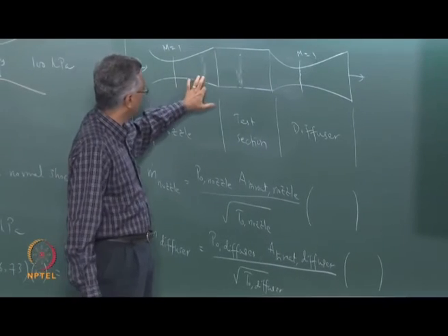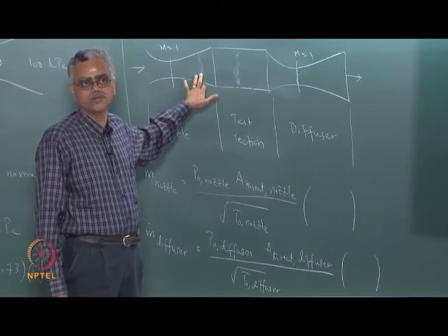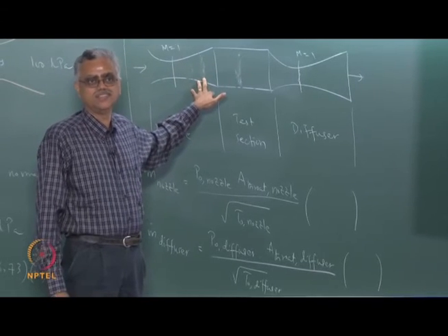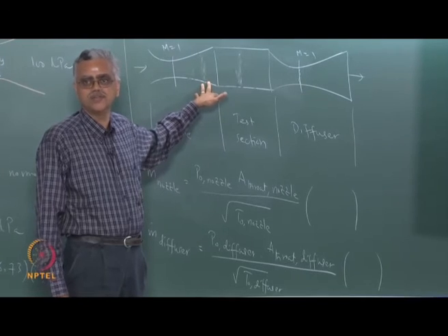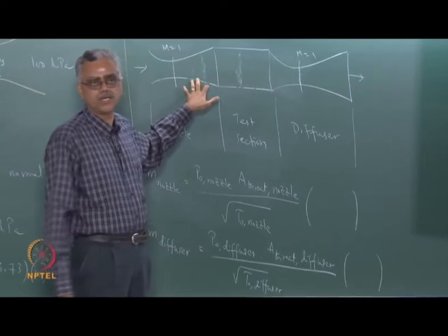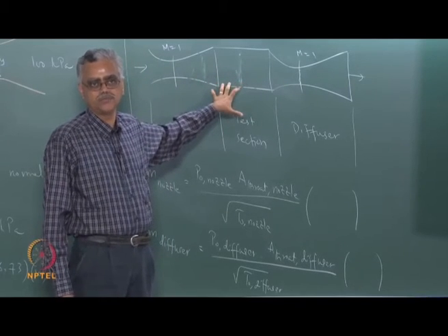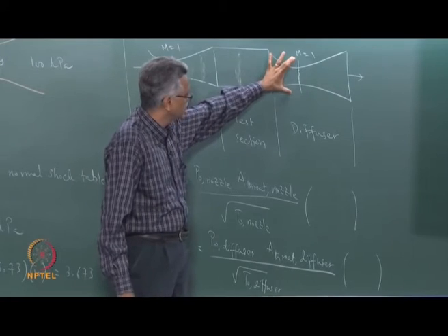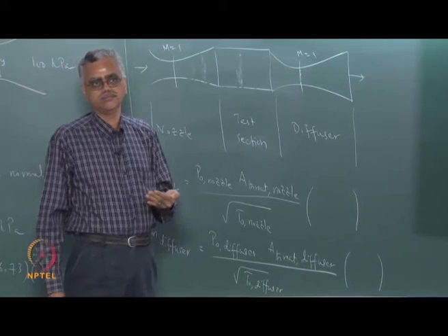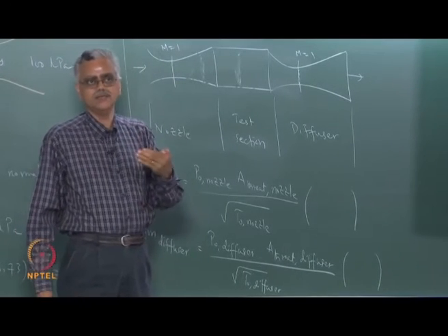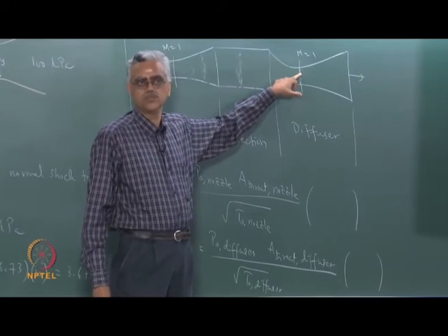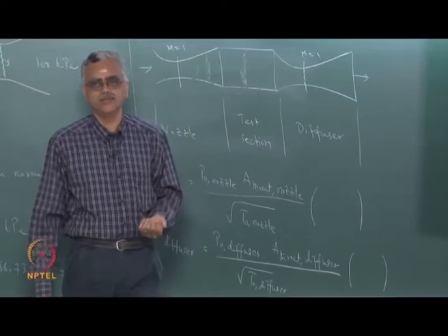And so, this starting shock in a supersonic nozzle poses difficulties wherever it is used. Whether it is a nozzle or a diffuser, it creates problems wherever it is used. So, we need to make sure that we understand the dynamics of what happens here, so that we can handle this properly. So, opening the diffuser to accommodate the normal shock is one strategy, but that is also mechanically very complicated to implement, right. You need to have throat areas which are movable. That is not so easy to implement in a mechanical sense in practical devices.